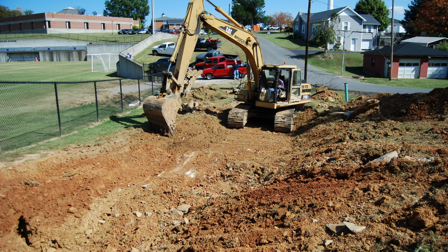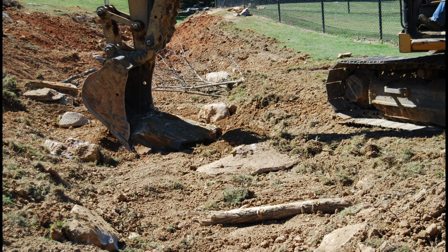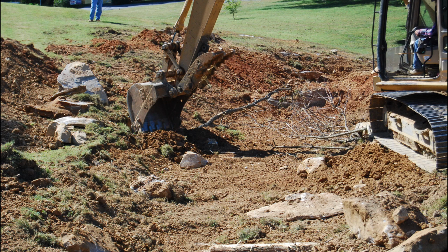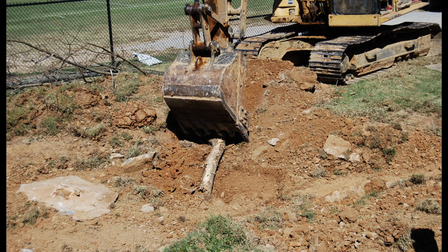After the soil was removed from making the floodplain, we shaped gradual slopes along the stream banks. We then placed the large rocks that were saved on the floodplain to provide habitat for animals. Ferris Osborne strategically placed the boulders so they would look natural in the shallow holes he had dug in the floodplain. The few pieces of woody debris that were available were also placed on the floodplain.